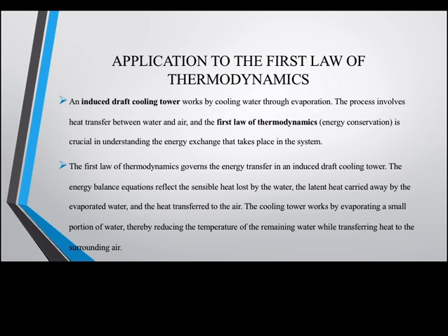An induced draft cooling tower works by cooling water through evaporation. The process involves heat transfer between water and air, and the first law of thermodynamics is crucial in understanding the energy exchange that takes place in the system. The first law governs the energy transfer in an induced draft cooling tower. The energy balance equations reflect the sensible heat lost by the water, the latent heat carried away by the evaporated water, and the heat transferred to the air. The cooling tower works by evaporating a small portion of water, thereby reducing the temperature of the remaining water while transferring the heat to the surrounding air.